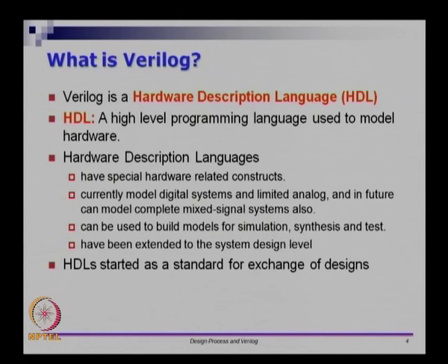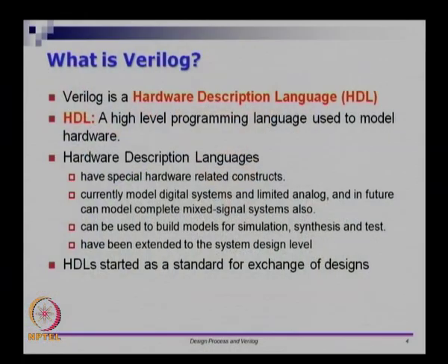I have a truth table, and you have a circuit drawn on paper and pencil. We have to now go through a whole process in which we have to interface and get everything working to design a complete system. So HDLs actually started as a standard for exchange of design ideas. If I write my description in Verilog, and you write your description in Verilog, we can take these two descriptions, put them together and make a larger chip. We do not have to translate from one to the other. That is the main intention with which hardware description languages were invented, and it became quite useful after that.